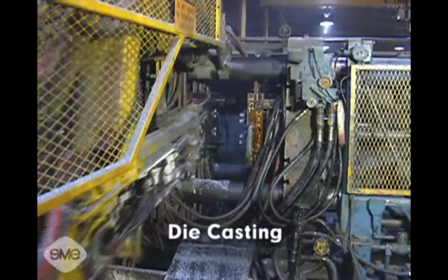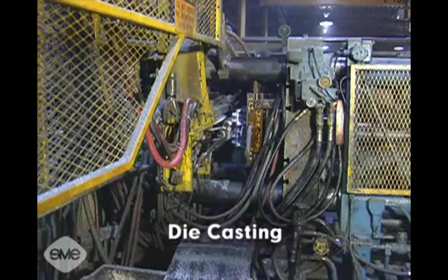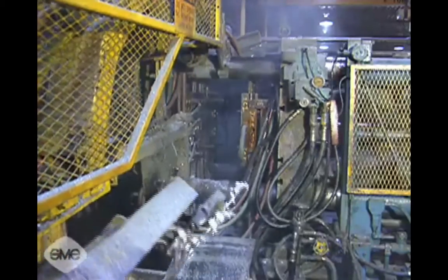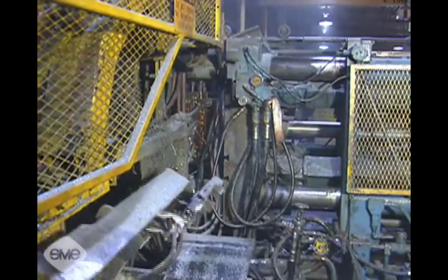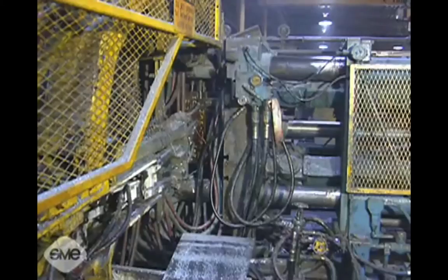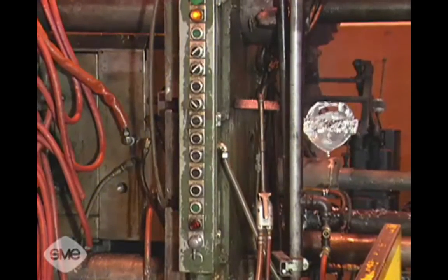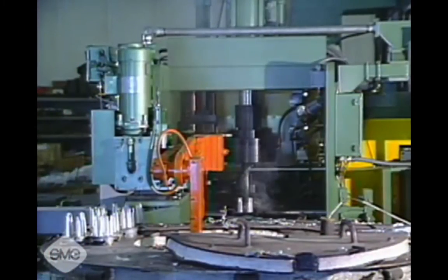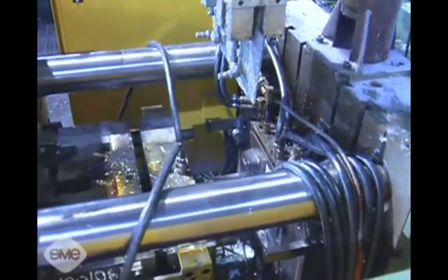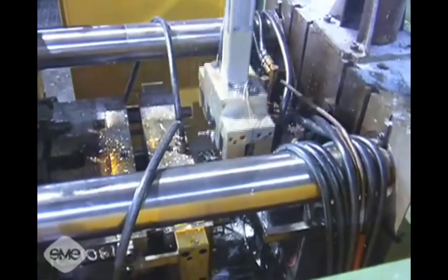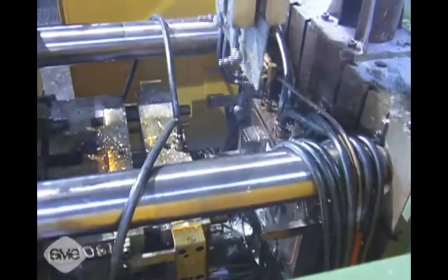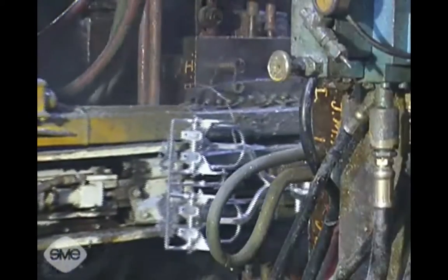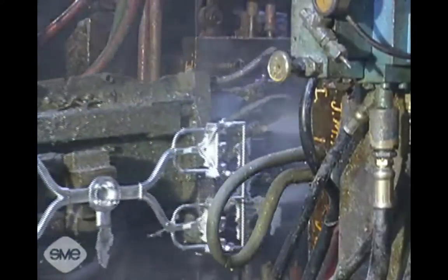Die casting is a rapid, high production process for simple or complex, often thin-wall, precision parts. Castings are usually small to moderate in size and cast of non-ferrous metals. The molten metal is forced under high pressure into the die of a horizontal, sometimes vertical, die casting machine. One die half is attached to a fixed platen, the other die half to a movable platen. Die casting can produce a single part or multiple parts in a single metal charge, also called a shot.